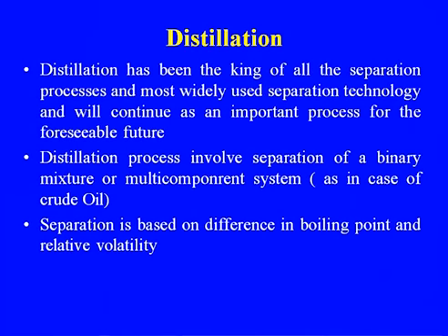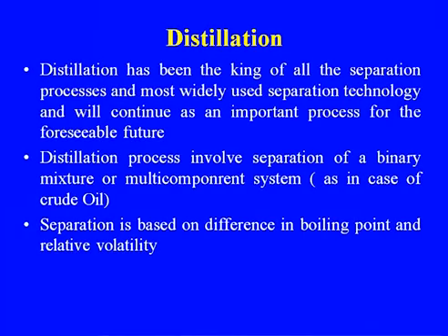continue as an important process in the future also, because you cannot imagine any chemical process, whether it may be petroleum or petrochemical, without the distillation column, because we are using distillation for the separation of the reactants. The distillation process involves the separation of a binary mixture or a multi-component mixture, as in the case of crude oil. Separation is based on the difference in the boiling point and the relative volatility.